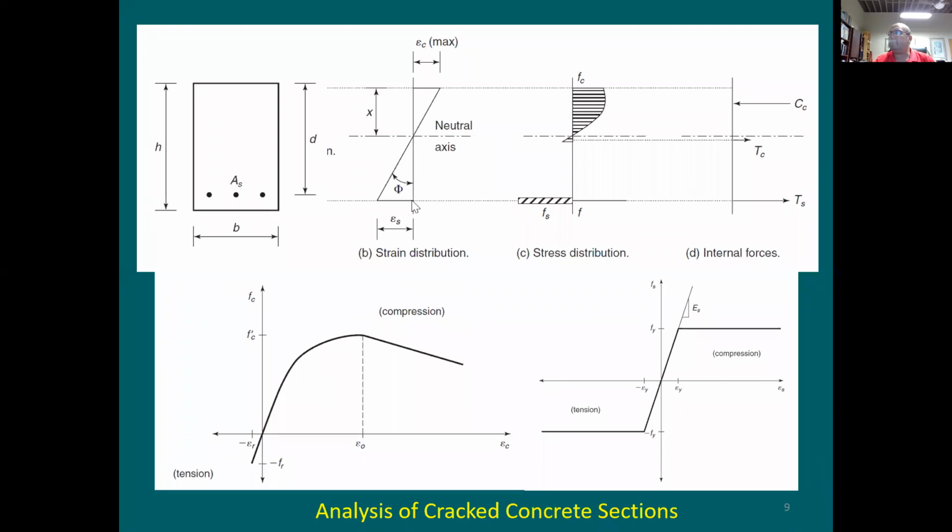concrete is gonna be cracking. That's my understanding. So concrete here is gonna be nothing. It's not gonna be working with you. But when you look at the tension side, you're gonna see here concrete is gonna be still working with you up to maybe like 400 psi. Correct? Like f sub cr, the tensile strength of the concrete. So in a little bit of here, concrete is gonna be still working. And right below it, concrete is gonna be cracking.